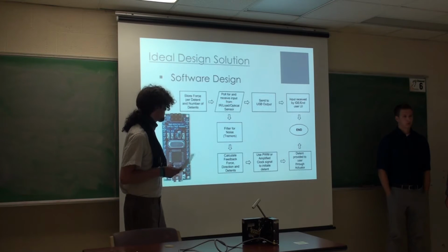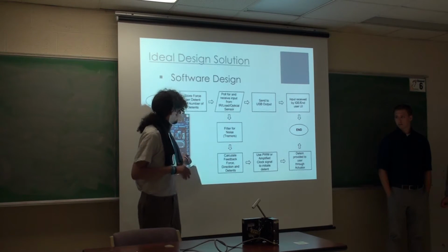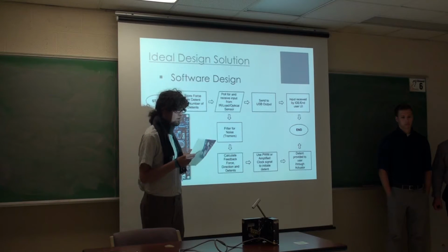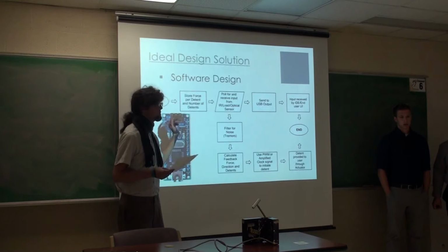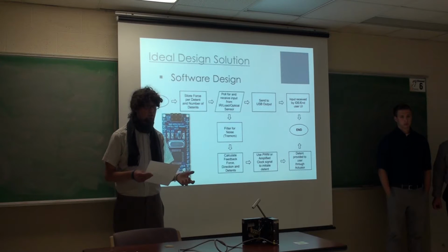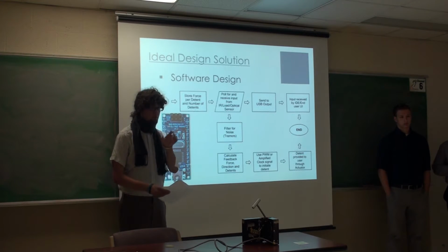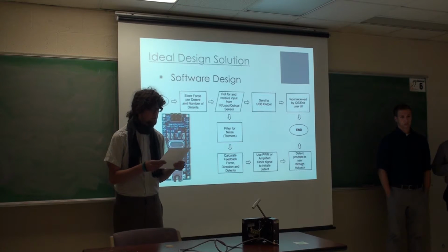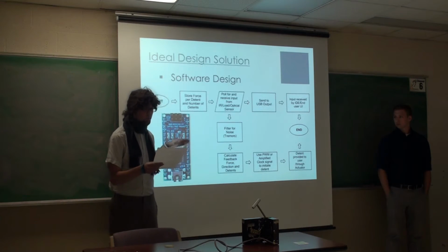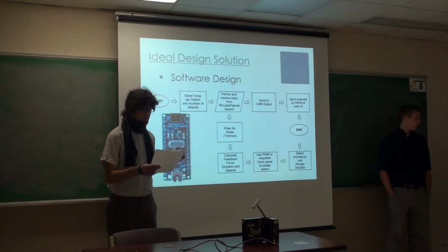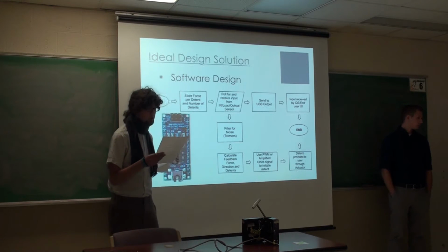We chose this setup because the actuators will move based on the number of detents and direct the force. For this data path, as I was describing, when feedback is sent, the actuators will be able to adjust by going in reverse, therefore creating feedback. So the user will know he has to apply a certain amount of force to get past each detent to move into the next one for navigation. And the load sensors we chose because they would give us that point where input would be registered, as seen on that graph before. This setup will allow us to control the number of detents that we need.